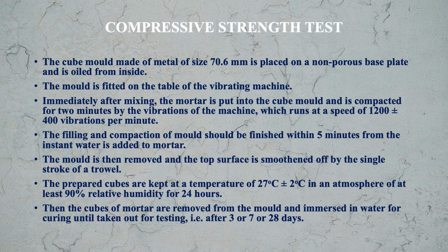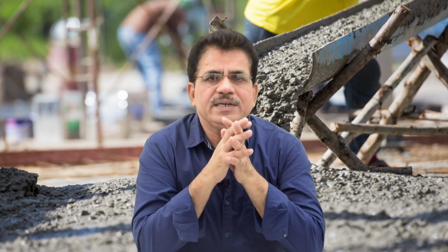Then the cubes of mortar are removed from the mold and immersed in water for curing until taken out for testing, after 3 days, 7 days or 28 days, when you want to test the cube. Next test on cement is the tensile strength test.